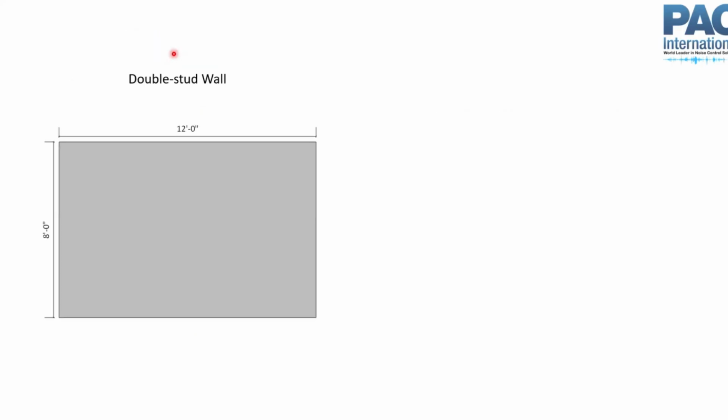And to really hammer home the importance of paying attention to all of these details, I have an example here. I talk about trying to build a soundproof space, and I hate that term because nothing's really soundproof. It just lets in less sound or lets out less sound. But if you're trying to build this space that contains sound, it's like trying to build a submarine, right? You don't want to let any water in from any direction in a submarine, and even a tiny little leak will sink the thing. And acoustically, even a tiny little leak can sink you from an acoustical standpoint.